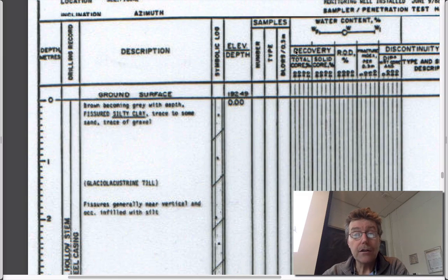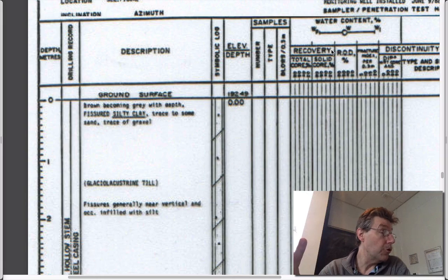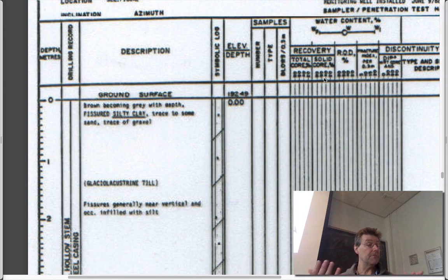And if it's a rock, the measurement would be in terms of how much core did you recover. So you drill 5 feet, do you get 5 feet of core, or do you get 3 feet of core? And so this would be the percentage of core that you recover. How much of it was solid in one piece, because that says something about whether you'd have fractures in there, which would be important in terms of its strength, but also in terms of permeability characteristics.